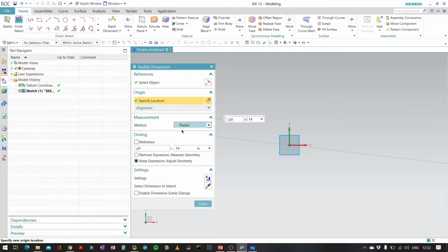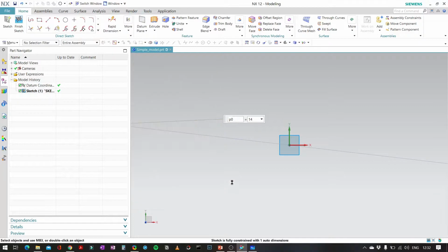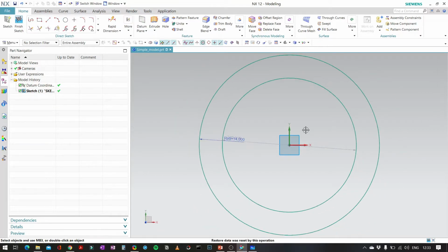For our reference, we are only entering it in radius, so we'll go with the radius. Now if you see, we have gone out of the space, so the whole drawing is out of the space. So we can hold Control and F, which will fit all the things. So now you can see the difference.